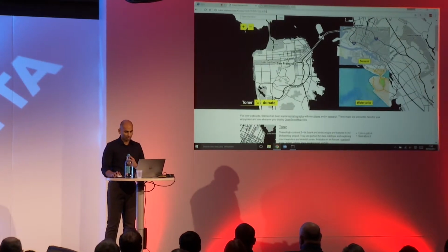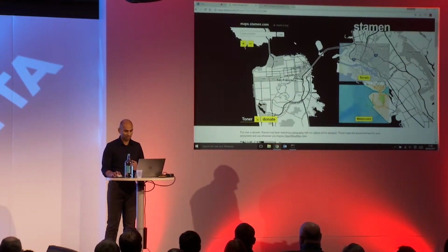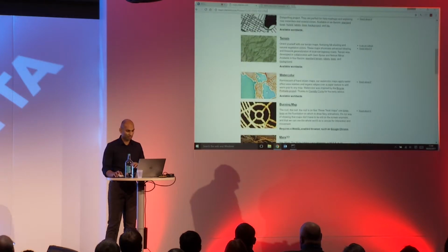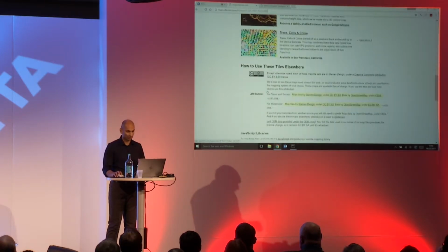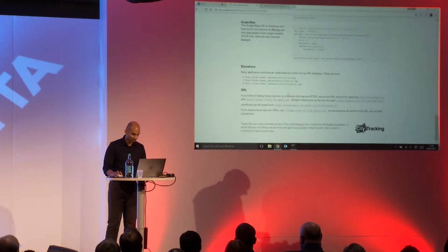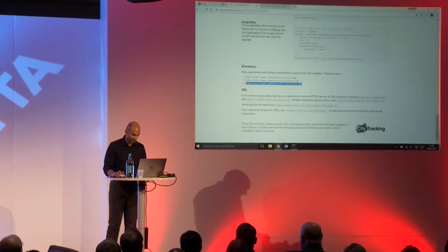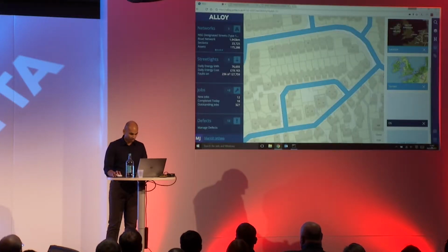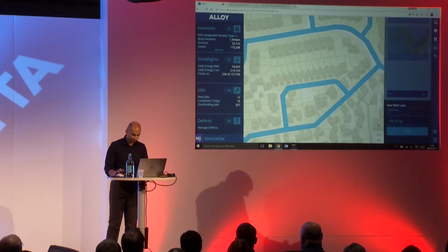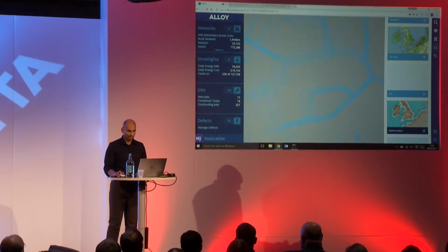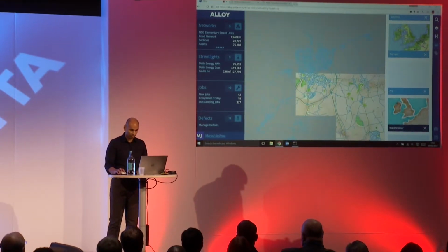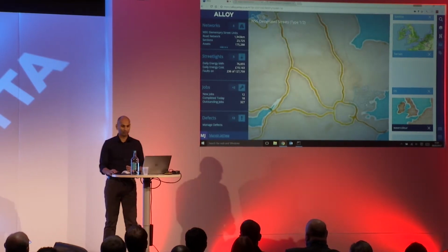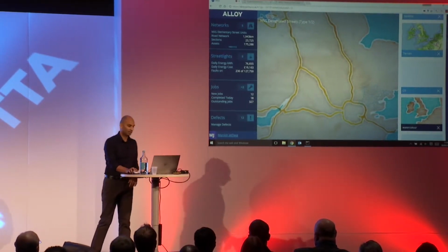So we've got an organization here that publishes WMS services. They've actually got some really beautiful maps like these watercolor style things. And what the hell, let's try and have a use of that one. So I'm going to grab this, which is their WMS service, and I'll just copy that link. I'll then add a new base map, give it a name, paste in the link, hit done, and that map is added. I can now view a stylized map of the UK that quickly.